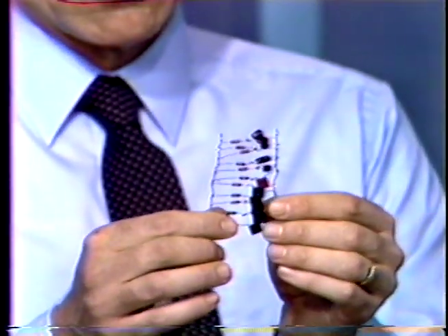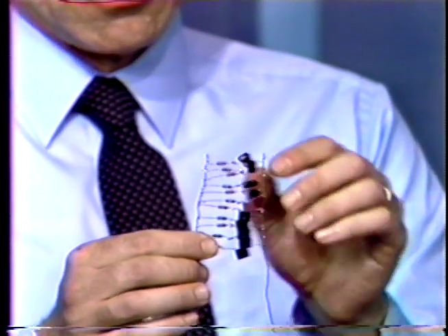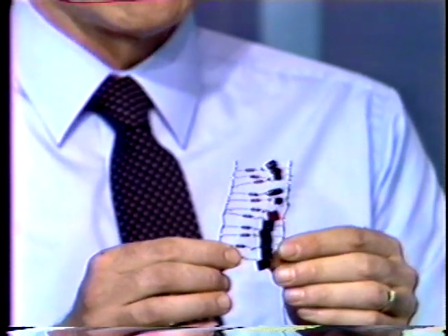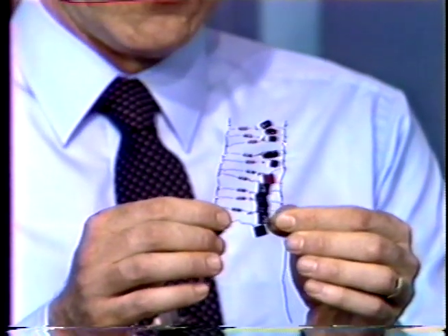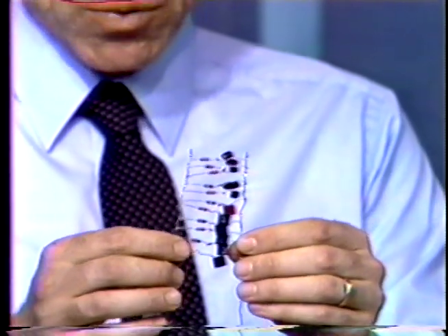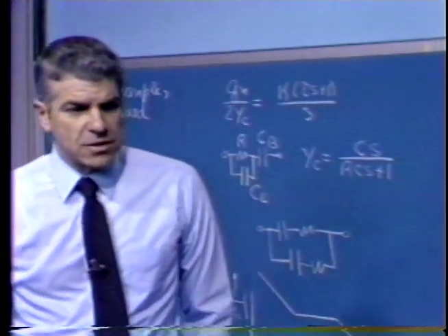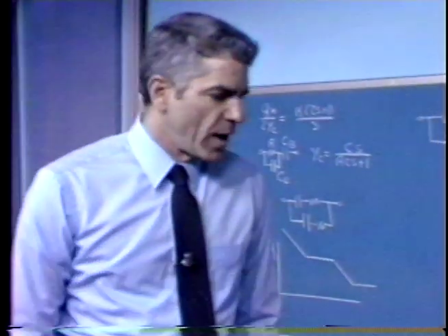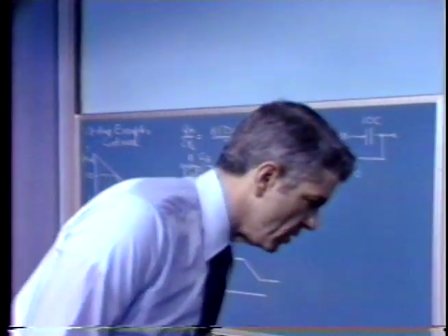Well, in order to see how that works, we've built up such a network, and here we have, they look a little bit unwieldy. This happens to be an 11-rung ladder, and what we have are, of course, simply 11 parallel RC sections. This network gives us a 1 over radical S roll-off from several megahertz to fractions of a hertz. Again, using 1 RC section per decade, we get that sort of performance with this kind of a network. What I'd like to do is investigate how that sort of a network stabilizes a system pretty much independent of where we locate an additional pole in the loop.